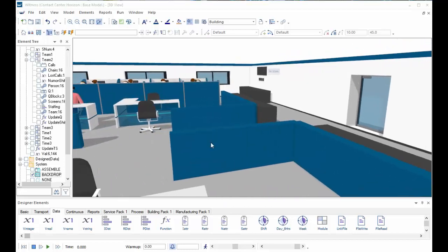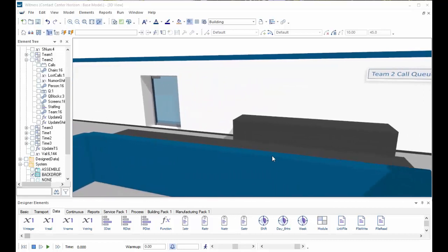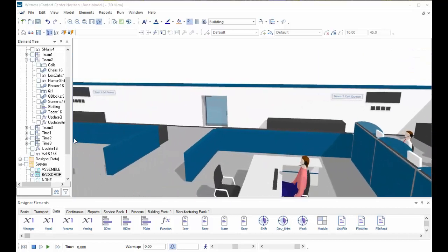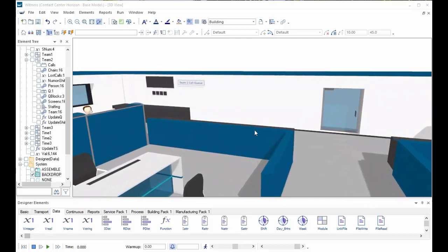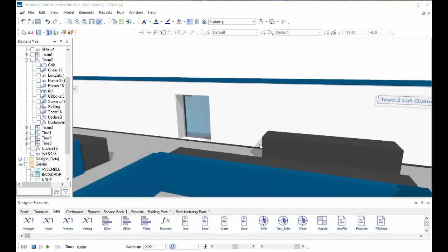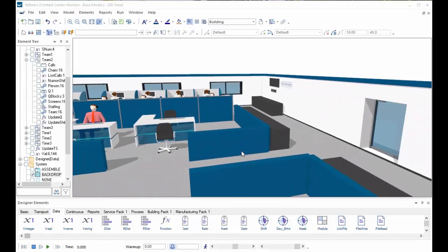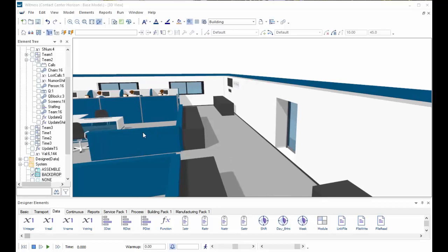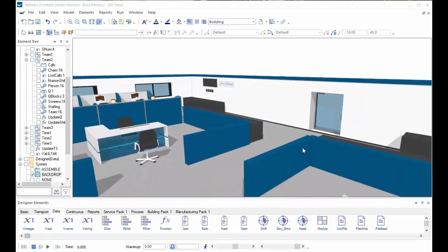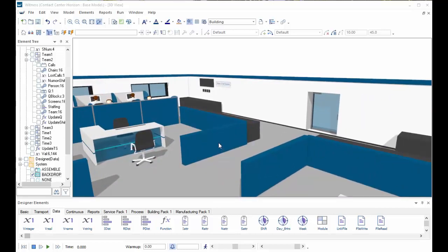And we see, actually, that doesn't look too bad, but you may want partitions of that width, but it's probably more normal to have partitions that are not quite that wide. It's another option for drawing a block of furniture, so you don't have to use a filled-in rectangle. An empty rectangle, by the way, will extrude a hollow shape, whereas the line and the filled-in rectangle will both create the filled-in shape as seen here.